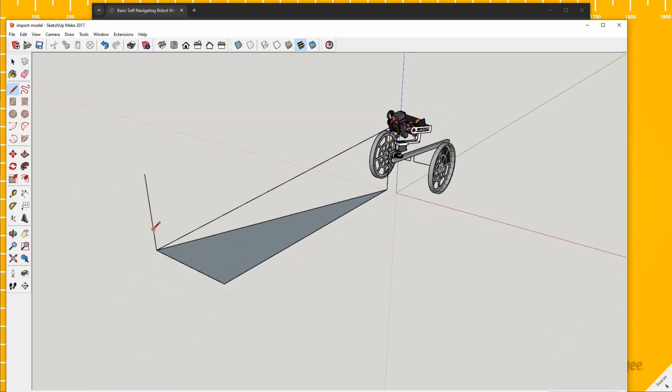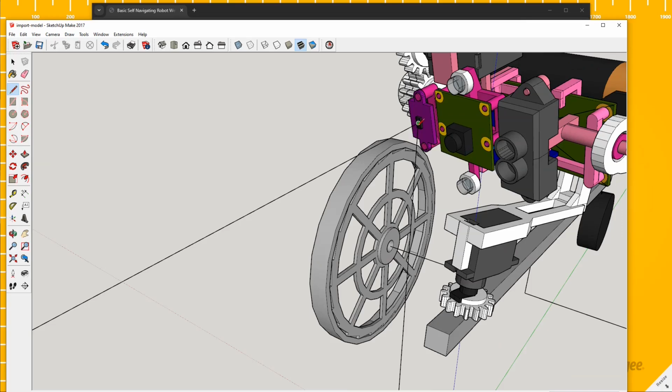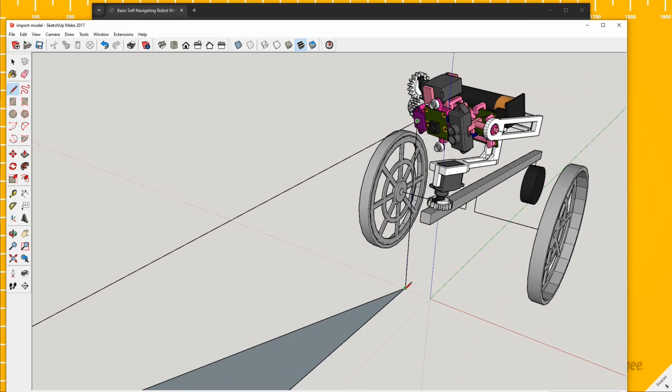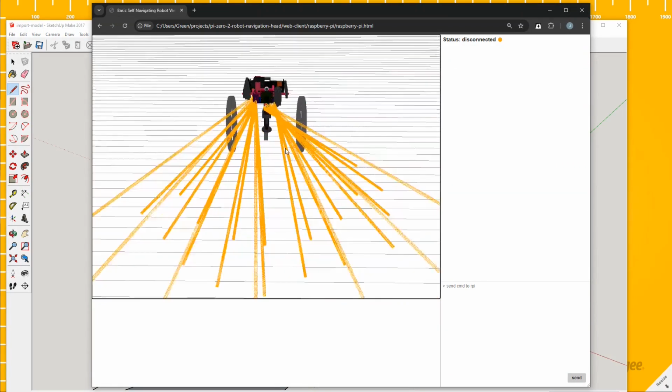And in order to get those coordinate pairs, you have to go here and be like, okay, that's 6.5 Y or Z. And that's the annoying thing too, in SketchUp and what I'm used to in the real world, Z is blue, but in 3JS, Y is the vertical axis. So I had to screw around with that.